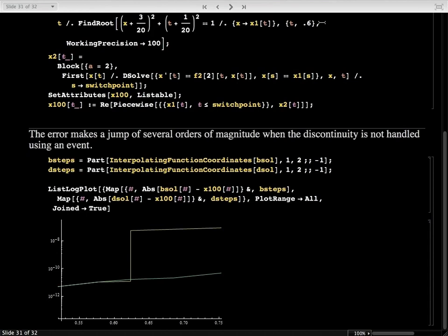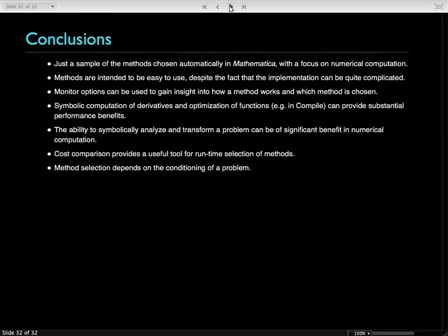And if I'm modeling a parameter or something like that, it's introducing this error throughout the whole interval here, which is, apart from the efficiency aspects of it shutting down the step size and getting into difficulty, it's actually introduced a huge amount of modeling error here. Whereas NDSolve, by analyzing that and by treading carefully around the discontinuity, was able to locate the discontinuity and then carry on the integration, giving a much smoother kind of error distribution.